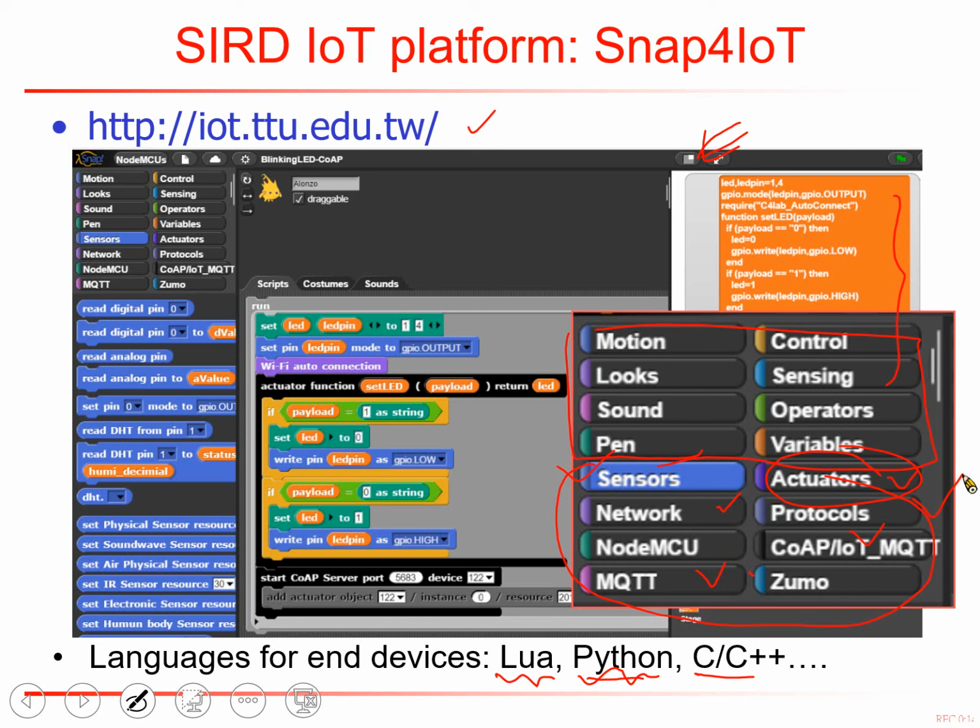So we can just use simple GPIO. Maybe you can write high and write low to the actuator, or maybe you just read 1 or read 0. You want to read something from the world with digital I/O. But actually, more than that, you can use I2C or SPI or UART to do more complicated stuff. So these protocols will be more advanced.